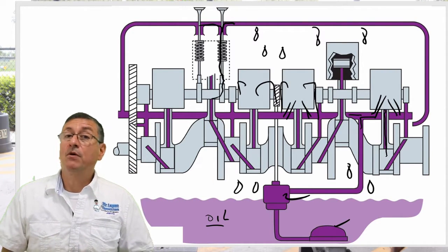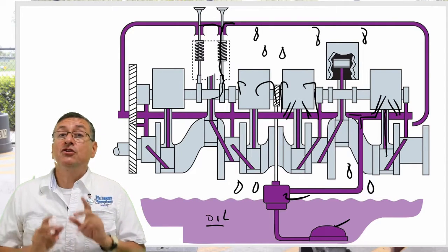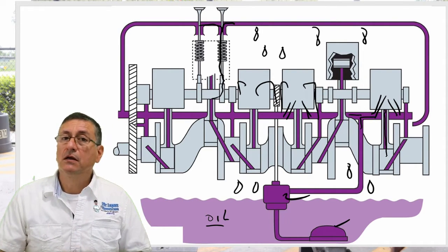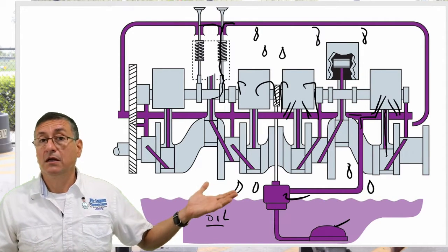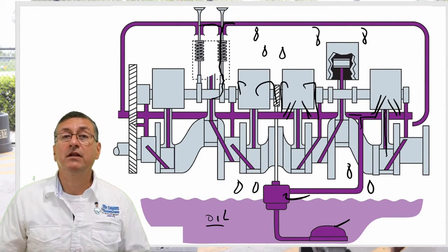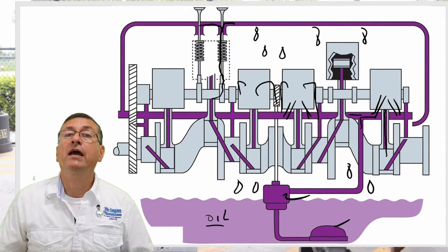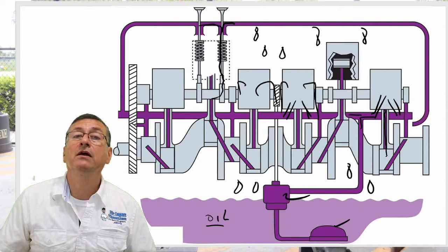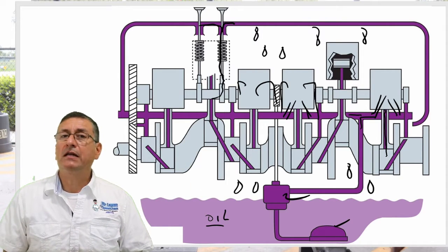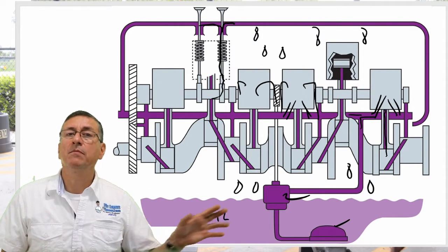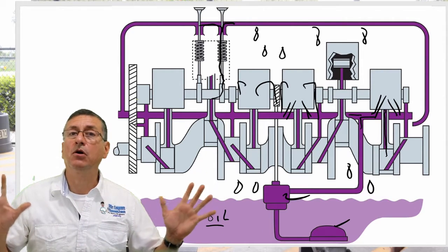Be careful. Probably the most expensive oil is not the appropriate oil for that engine. What year is that? Oh, this is an old diesel engine, 1984 or 1973. Okay, what type of oil do you want? No, I want to use the full synthetic, the new one. No, probably that engine originally, the manufacturer recommended mineral oil.